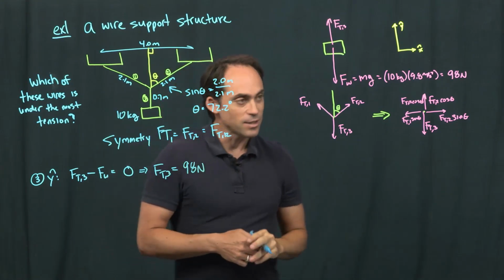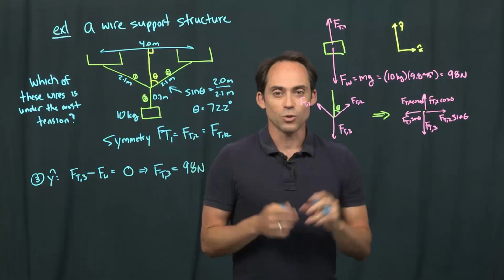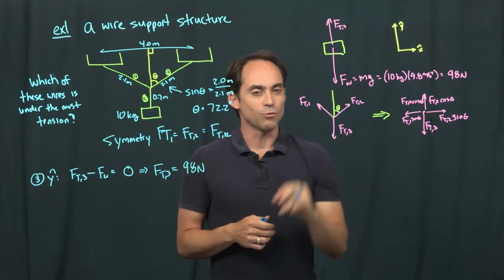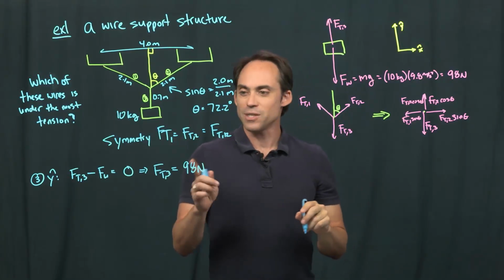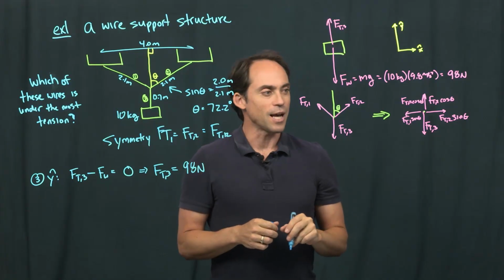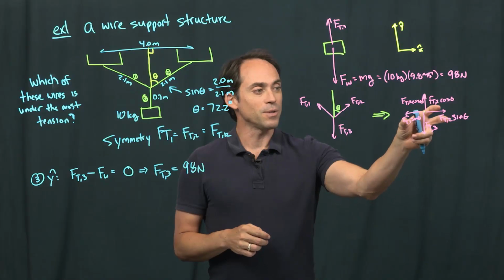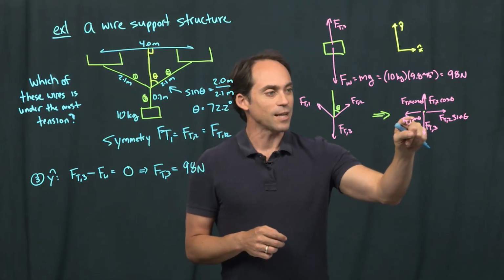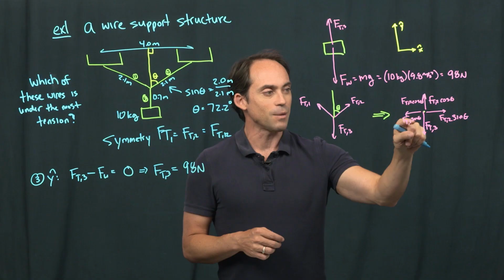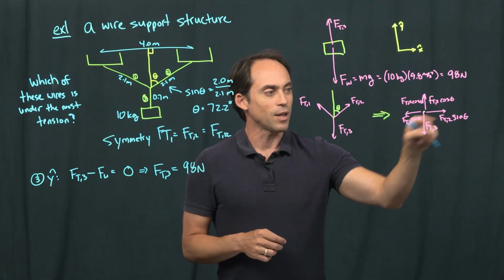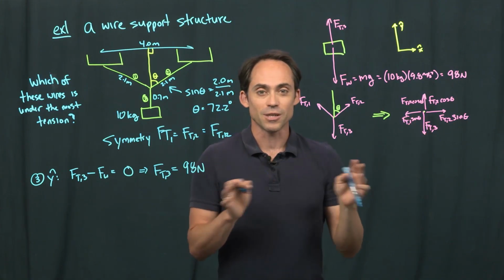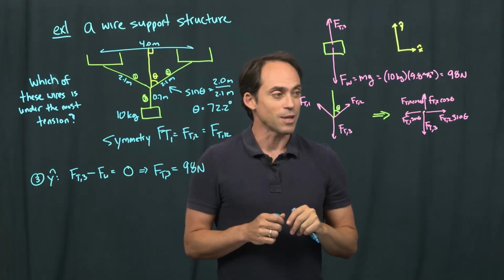Okay, so now let's take a look at a couple different axes for the next force diagram. I've already said that the tension forces along both sides are equal to the same thing. In fact, we could have actually solved that from this force diagram, because notice that along the x-axis we have FT1 sine theta pointing in this direction, FT2 sine theta pointing in that direction. Those sum up to 0, so they have to be equal, right? Those magnitudes have to be equal.